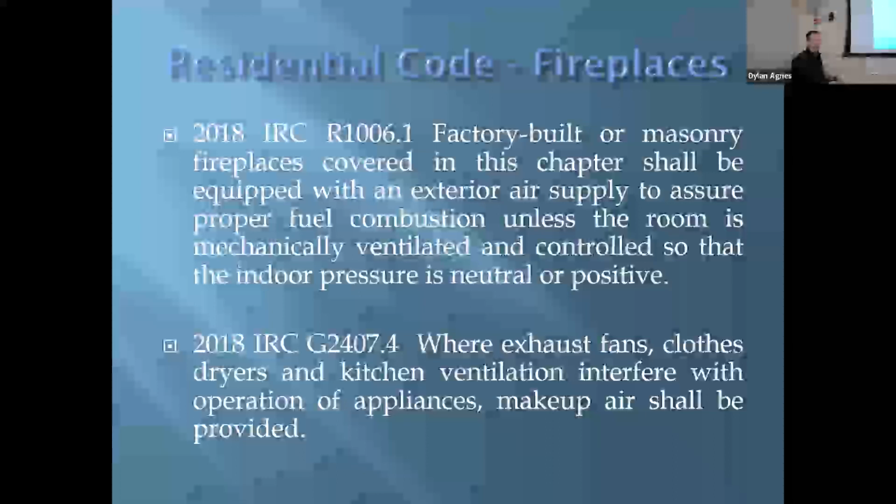The most negative house I ever tested was a fairly airtight, intentionally airtight house in Coeur d'Alene that pulled -49. Wow. So essentially the fireplace would be sucking. It becomes makeup air for the house.